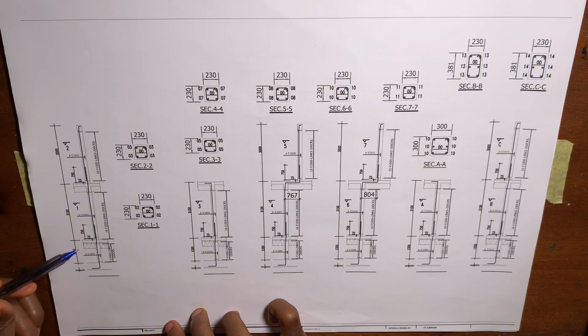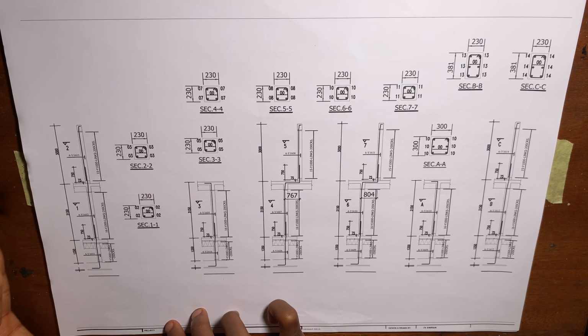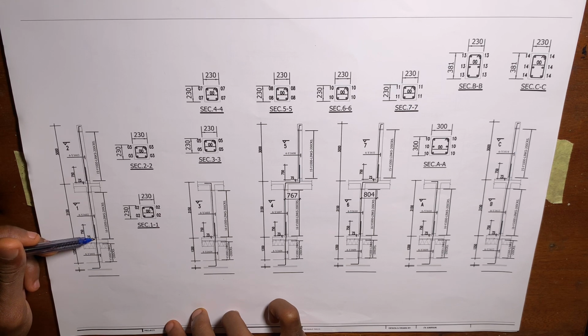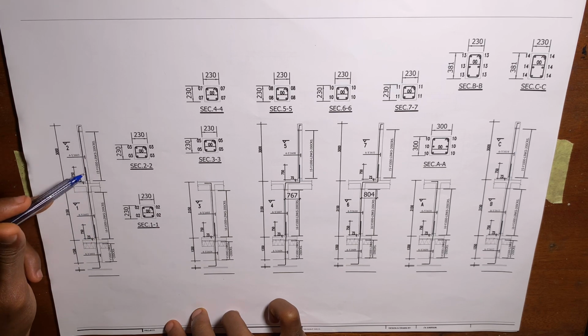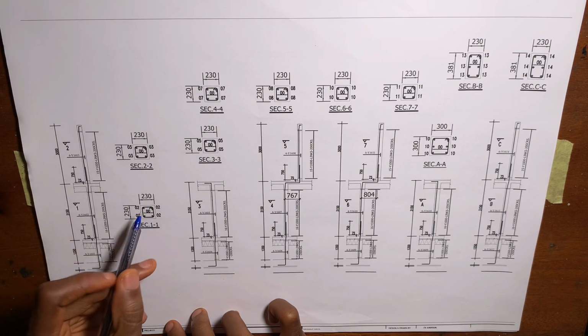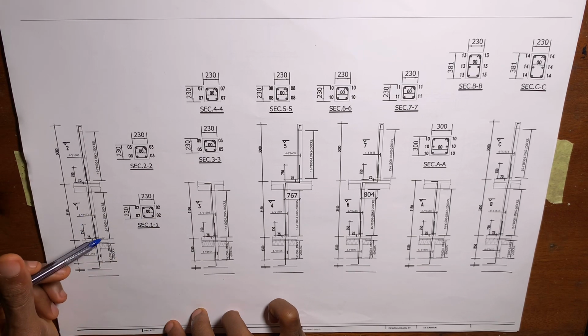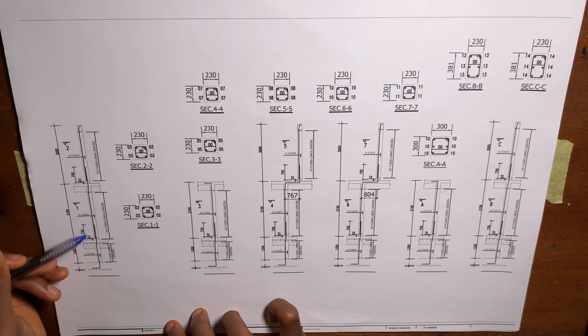The same thing that we did here is the same thing we're going to be doing in the superstructure, but our main focus is the substructure because that is what we want to measure. If you can see the superstructure, the column post from here goes up. It says 4y16, the same thing you can see here. There are 4 vertical bars in number, and then the links from here to here is where we're going to be seeing our links.